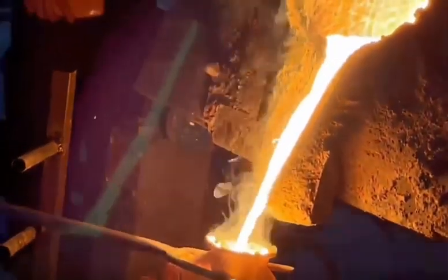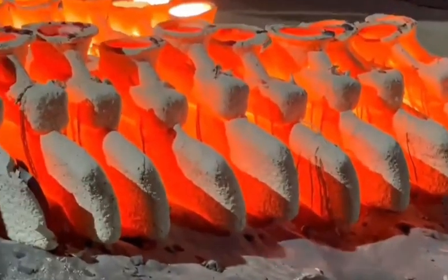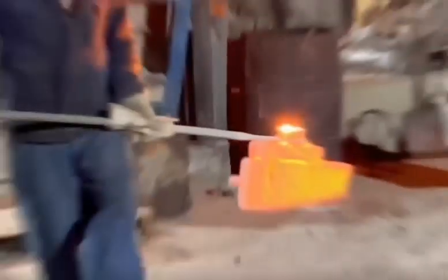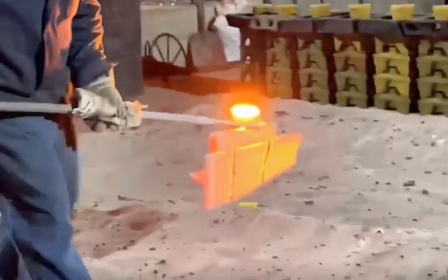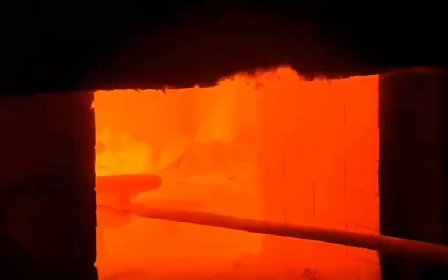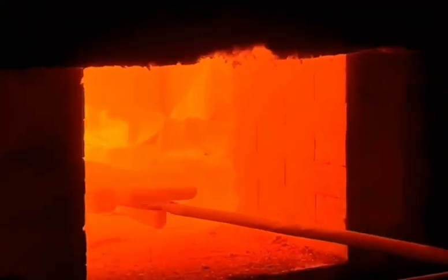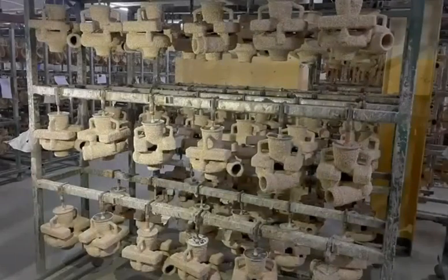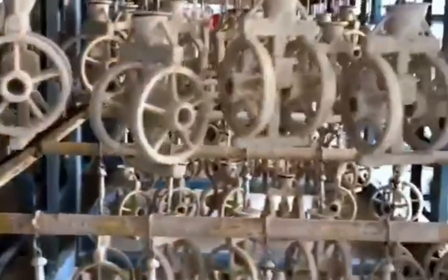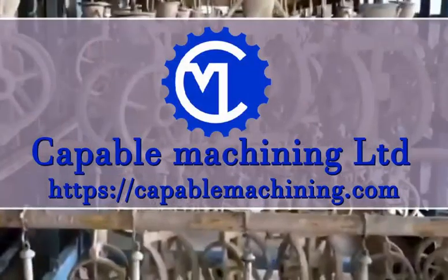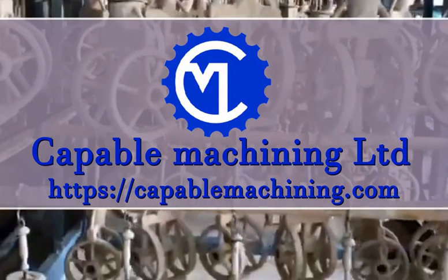In conclusion, both investment casting and die casting have their advantages and disadvantages. Investment casting offers greater design flexibility and material selection, and is well suited for complex shapes and smaller production runs. Die casting is better suited for larger production runs and has fewer size restrictions, but is limited to simpler shapes